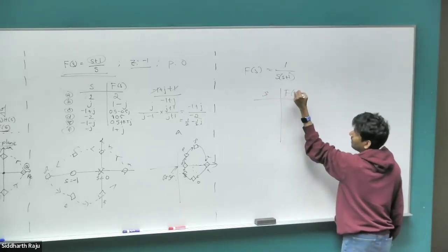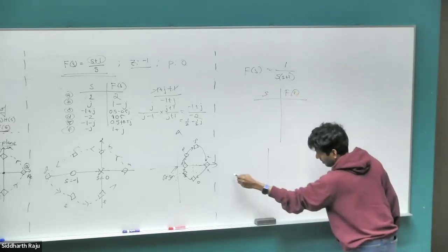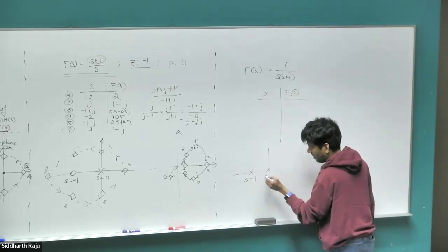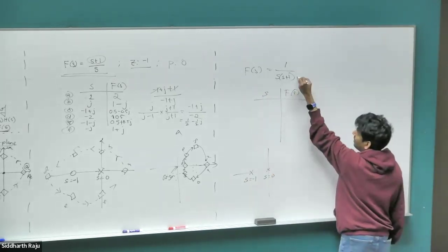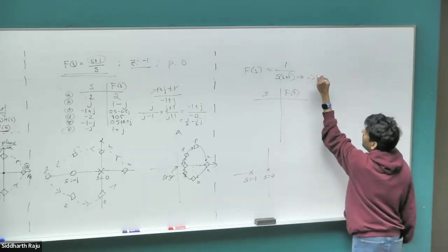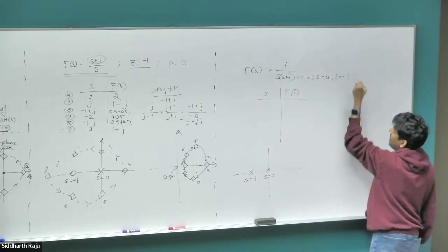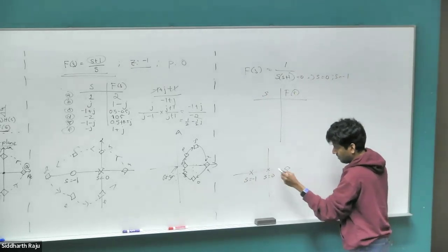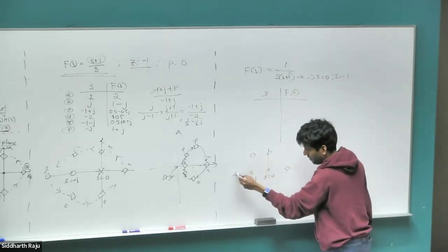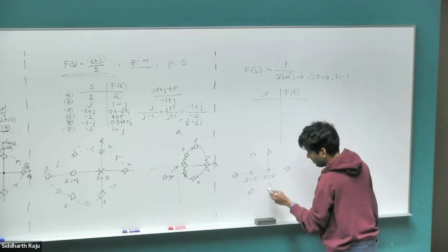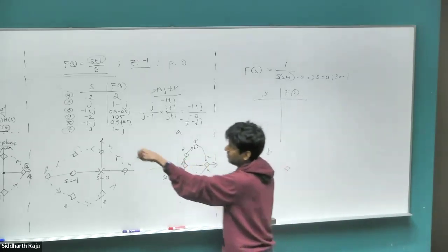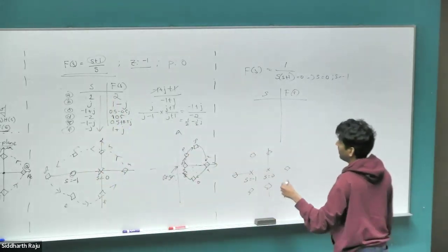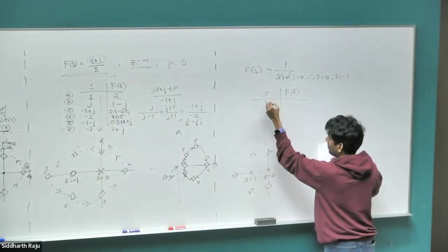So we have f of s. And in this case, the poles are at s equal to -1 and s equal to 0. Again, the poles are solutions to the characteristic equation, the denominator being equal to 0, which implies s can either be 0 or s can be -1. Right? So we are going to pick the same set of points as before. Enclose them. The same set as whatever I had here. So the only thing is I replace the 0 with a pole, and I'm going to see what has changed right now. So the same set of values, let me just give you the answer.